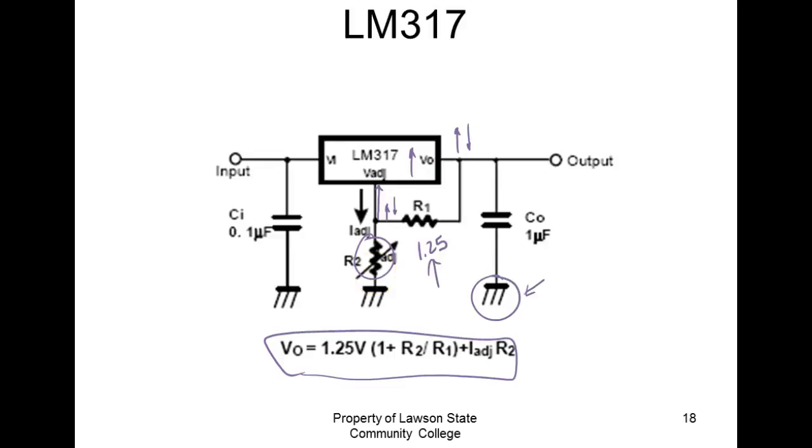So if I had a 1/4 watt pot, then we would calculate the minimum and maximum currents that we would put through it, right? You understand what I'm saying? So if I adjust this all the way down to 0, then the amount of current flow we would get would be the size of this resistor flowing through the pot, right? Does that make sense? And we want to make sure we don't exceed the wattage rating on the pot that we put down there.